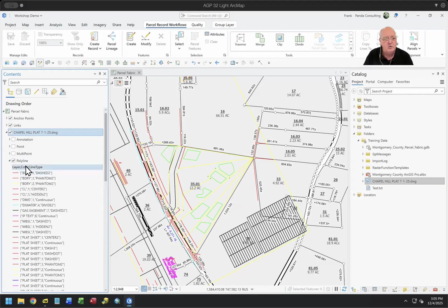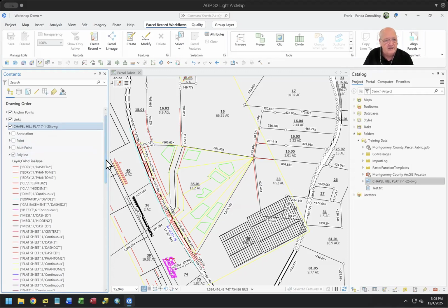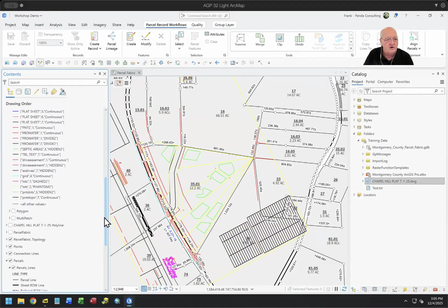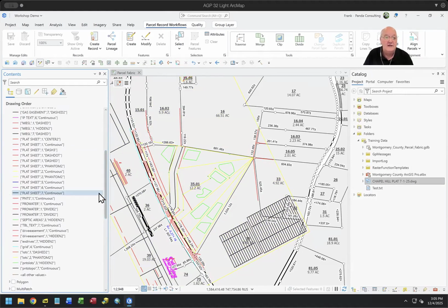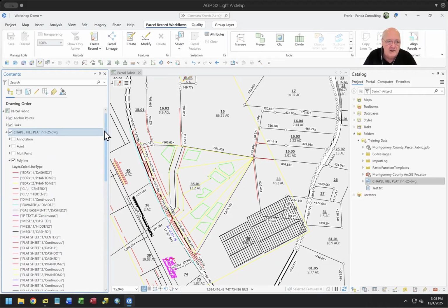If I open up that polyline, expose that polyline feature class and look through it, this is the layer structure that I get. And often we have no idea what these things are. So we start fumbling around and seeing how we can find specifically the lines that we want. So here's my first tip: rather than bringing all of these in, even though you might not be displaying it, it's still loading it in.